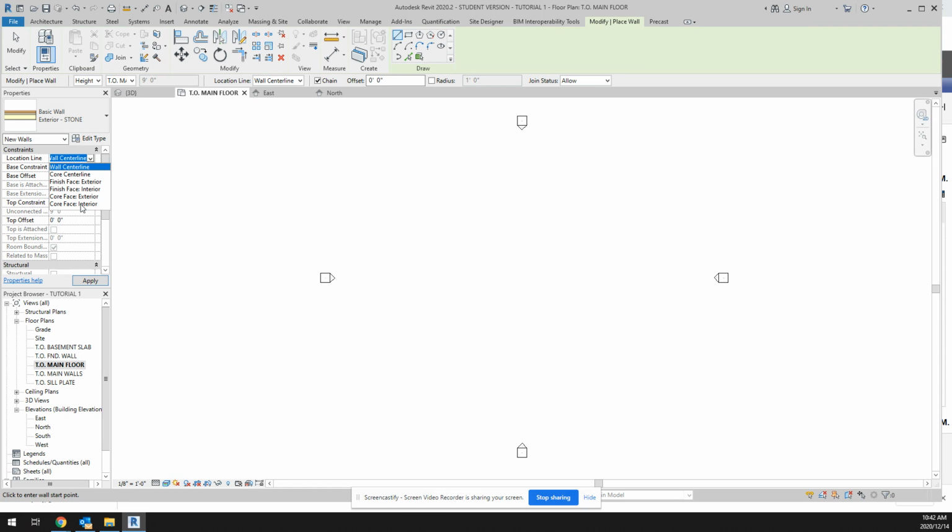So whatever values you enter in terms of your dimensions are going to be that finished face interior. So the interior, so the drywall of your building. So if you've decided that one of your rooms is 10 by 10 and it happens to be in the corner of the building, then you're able to enter those values and it'll give you an exact 10 by 10 dimension for that portion. Now, obviously, again, you have to add in your interior walls that form up the actual spaces that you're creating. But as you go around your building, you should be able to put in the values pretty close, if not exact, to what they need to be for your plan.